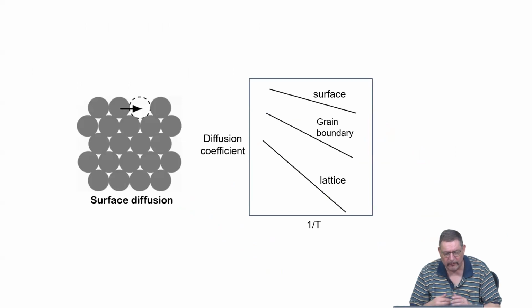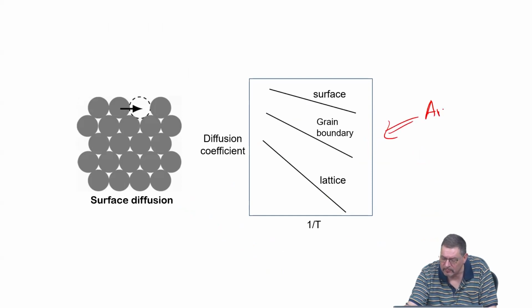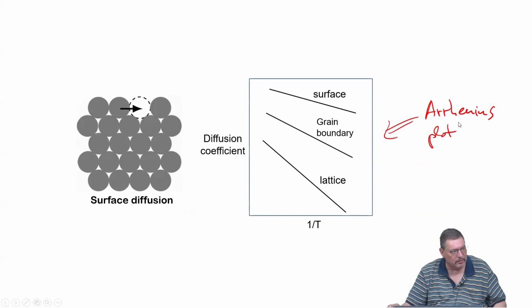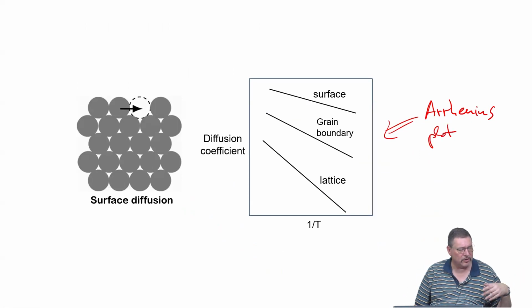And if we compare now substitutional diffusion and surface diffusion, I already explained, there is no atom on top, so it's very easy for the atoms to diffuse. Then we have in this Arrhenius representation, where you plot the diffusion coefficient as a function of 1 over the absolute temperature, from the slope of these lines you get the activation enthalpy.